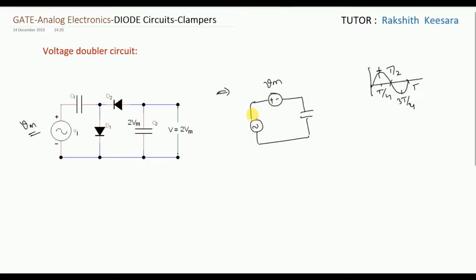So now this is the equivalent circuit, guys. It is the input voltage Vi. Now let us take it like this. See, this is our capacitor voltage. Since this is the direction of current flow, this is our capacitor voltage, so I am writing this as Vc. Apply KVL here. What do you get? Minus Vm plus Vi plus Vc equal to 0. So what will be the Vc voltage? Vc equals minus Vi plus Vm. This is the capacitor voltage.